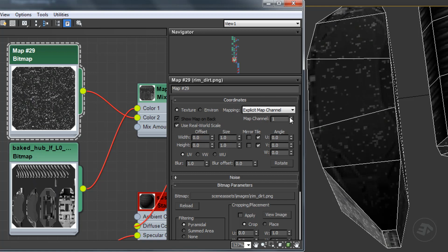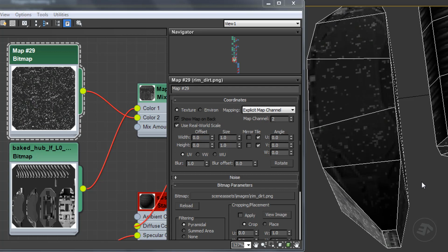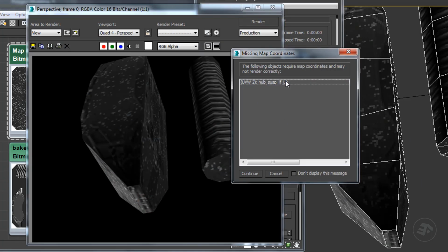You can change the wired UV channel of the selected material from the material settings. However, when you do render the 3D object, after changing one of the assigned materials UV channel, you will get this error message. You will eventually see this message because we did change the map channel from channel 1 to channel 2. But we did not create any UV map inside channel UV2 to render it usable.